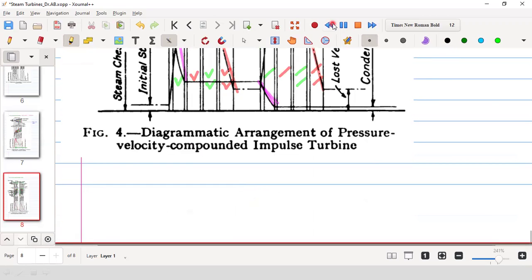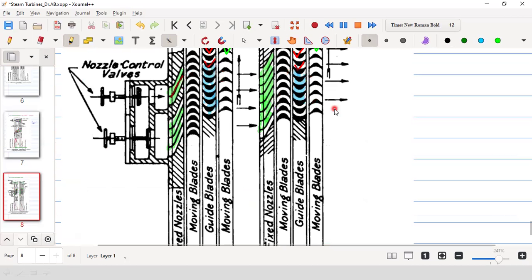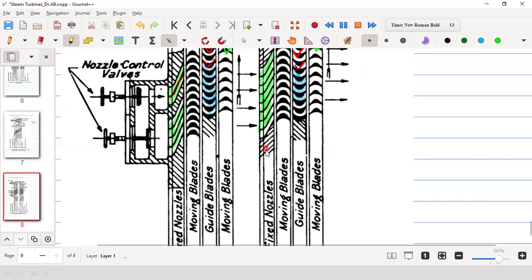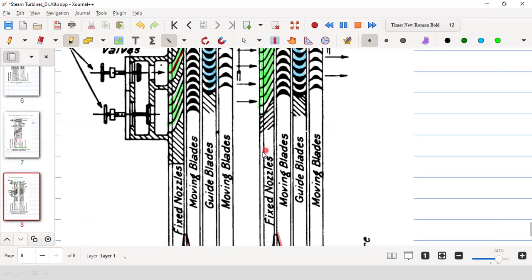So these are all isentropic flow? Yes. Theoretically, it is isentropic. Practically, it is adiabatic. There will be some friction, so frictional losses will be there, but more or less that will be considered adiabatic. Isentropic means reversible adiabatic, but it is not reversible due to friction, though it will almost remain adiabatic.